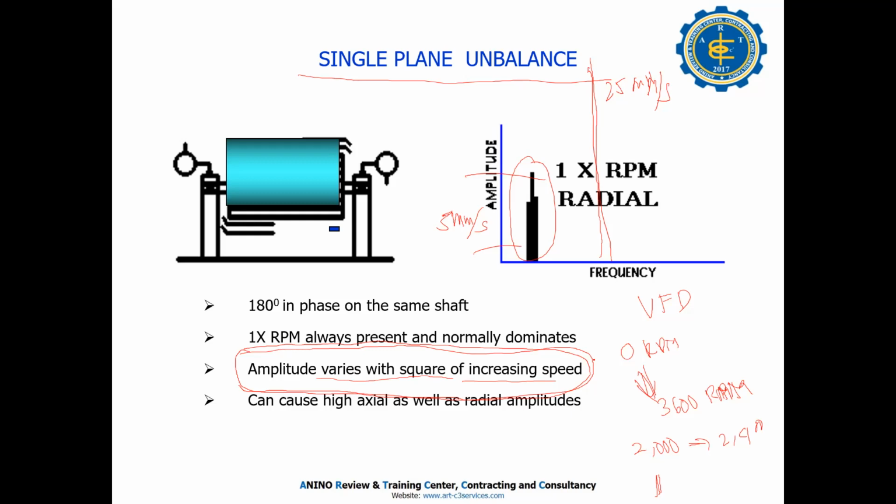Personally, I can prove it with a fan. We had a problem with unbalance. We shut down first, because the management or another department said it was not unbalance, so they changed the bearing. They had to fix the mechanical issues. Then we ran again with the same high vibration on X. Then we increased the speed, and the vibration went high.